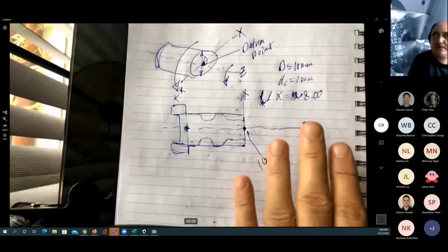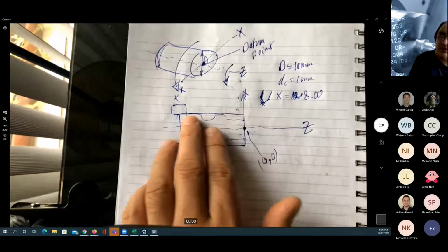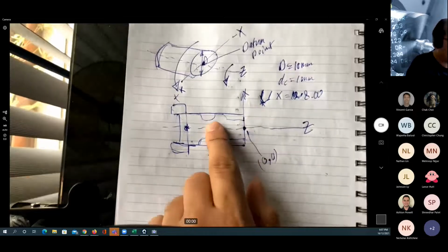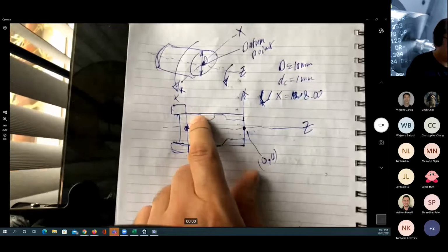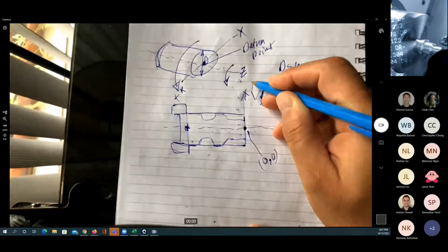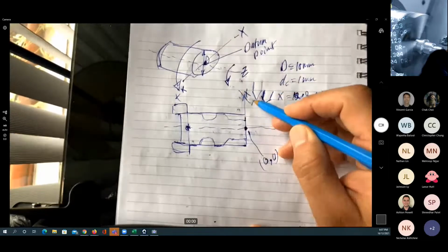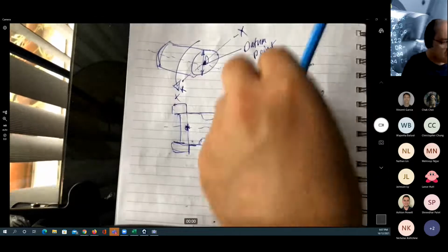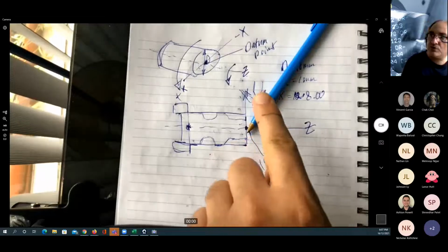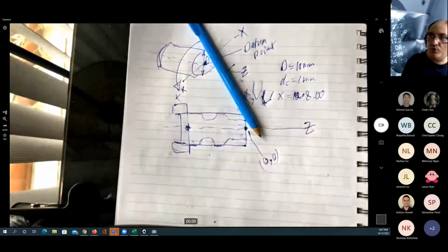This one is going to be left-handed because it's pointing to the left. We move it from here to there to make my cut. This cutting tool, unfortunately, will not be able to cut the circular shape. We have another cutting tool that is straight, and another that is right-handed. It depends on which direction the tip is pointing: to the left, neutral, or toward the right.